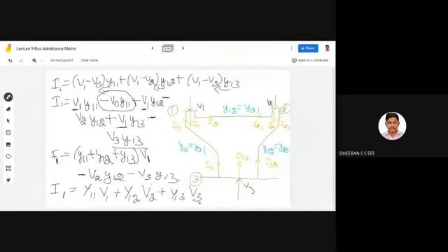So how this comes is, this entire matrix corresponds to your self admittance matrix, and this corresponds to your transfer admittance matrix, and this also corresponds to your transfer admittance matrix. How it is possible is using the formula. So are you now clear with this? We are just omitting this reference value of V0, and we'll be getting this equation. So consider this equation to be your first equation, and take this equation to be your second equation.